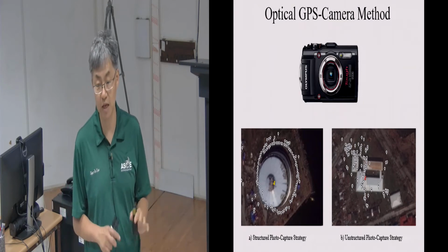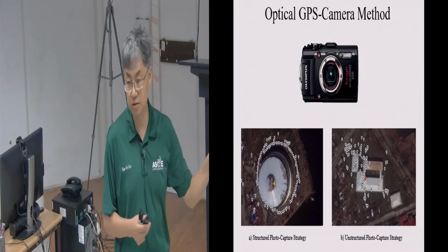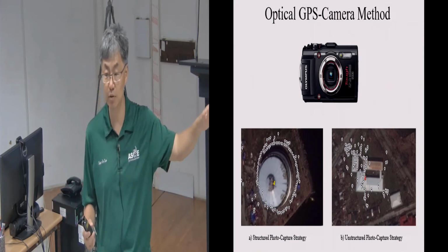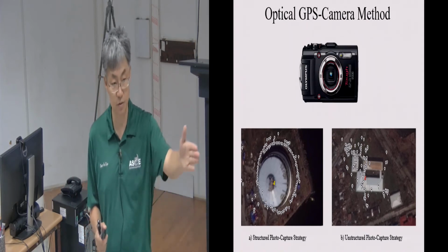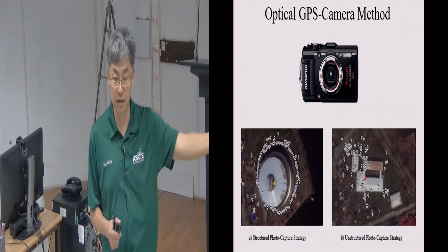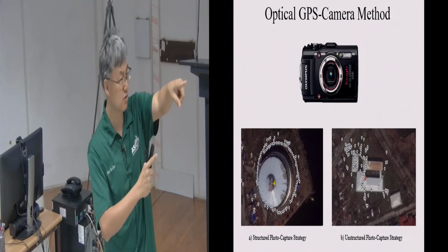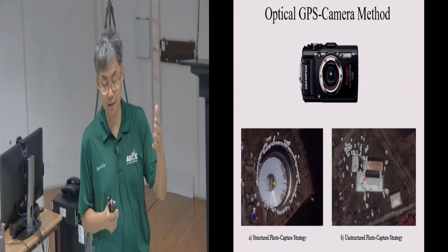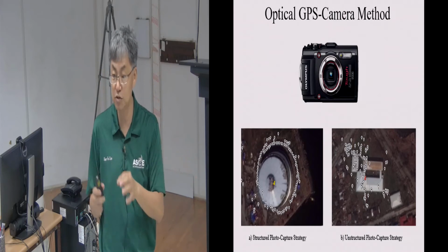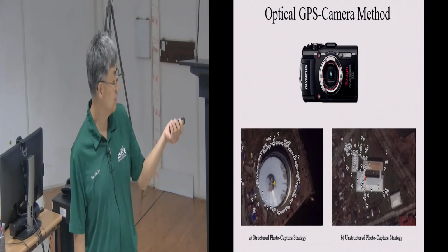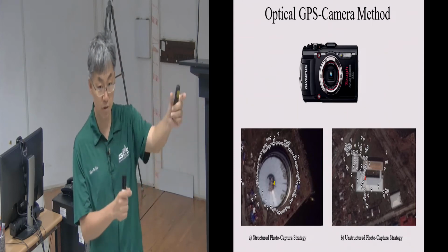You can see the scattering of all this. Why? Because we have 10 people on the ground, everybody with one of those cameras. People are roaming around because we have to investigate 10, 20 buildings in a day. So it's very busy. You have to drive through debris, go to one building, another building, in a very foreign environment, and everybody just focuses on taking pictures of cracks and stuff. So how can you go back and analyze more than 20,000 images? Which picture belongs to which building? We found that the GPS technology really comes in handy, because we were able to relate the pictures to the buildings.